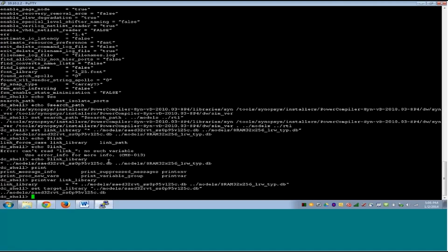It uses the standard cell libraries. It does not use memory libraries for mapping. A memory is a hand instantiated cell. That means if you want to use a memory, you should instantiate it directly in your design. There is no way DC can map a complex logic to memory. That is why a target library should contain mostly the standard cell library.